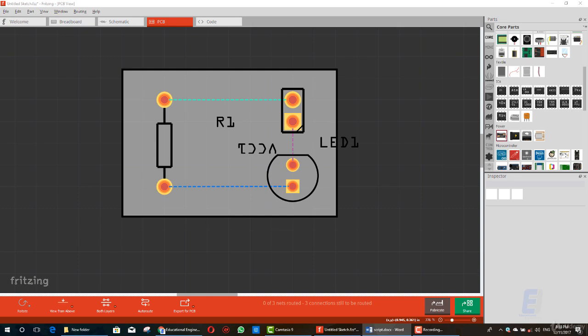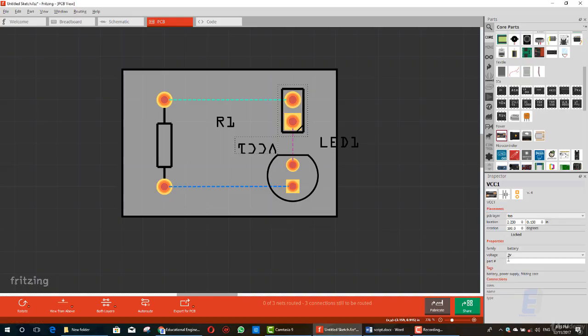Click on any part of this board and bring your mouse to the lower half of the toolbar where the board customization option appears. Go to the layers drop-down menu and select one layer. One layer means that our PCB will be a one layer PCB. As you can see, this is our PCB. It's asking us, is this a top or bottom component? These items are on top, so we need to deal with them as if they are on top of our PCB design.